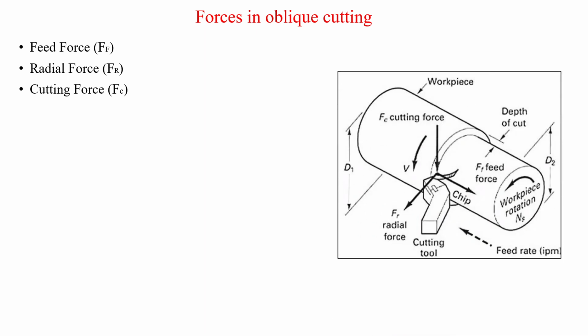See, this is the workpiece. This is the tool. So we are turning it. This was first the workpiece diameter. This diameter has been reduced from D1 to D2. Now see what happens in the turning process. The workpiece rotates at a spindle speed ns, and the tool is moving in this direction by a feed rate f, right?